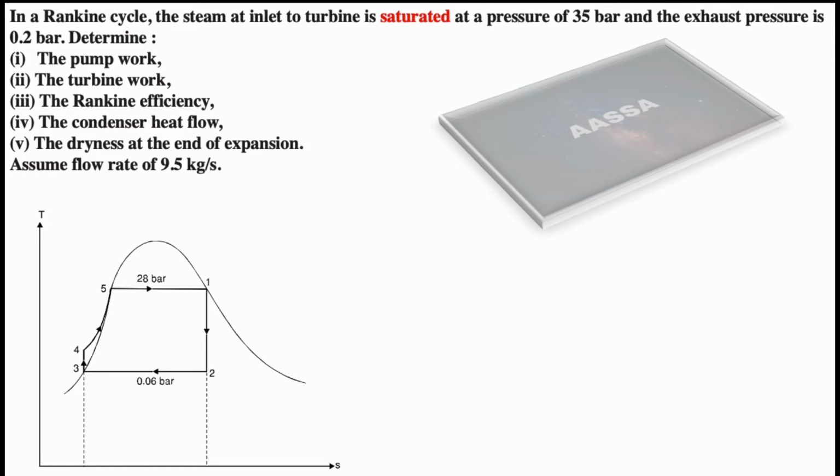State 2, we're going to have a condenser, right? So the turbine is being rotated by the steam. When it comes to the condenser, we're going to have fluid. And state number 3, we're going to have a pump right there. And on states number 4 and 5, that is going to be the boiler. They're going to boil so that we can have the steam at the turbine. So the cycle is going to repeat. So that's what you have.